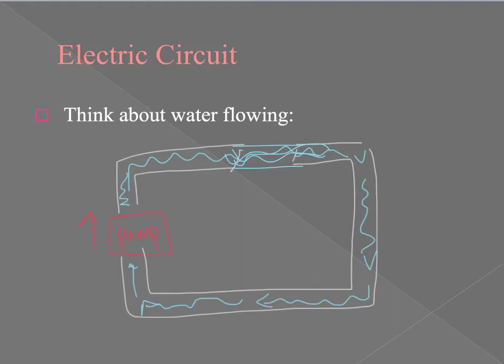So if we take a closer look, we can have many different options, but what we must always have is what we call closed loops. And this is for the reason I was just talking about. So we can have circuits like the simple one we saw just a minute ago where I have a battery, and this time I'm going to have 2 cells just for fun, and our resistor. This is a very simple one, and we have one loop. And it's a closed loop because all of my current can flow all the way around. I've got my voltage and my resistor. But we can actually have any number of loops as possible.